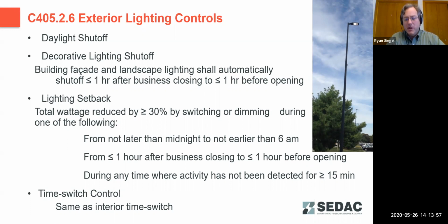Also, something else to be aware of is particularly with LED fixtures, they are sensitive to heat. And so we want to make sure to not be operating them during the hottest part of the day, which will extend their lifespan too. So a nice benefit of having that is to extend the life of your facility.